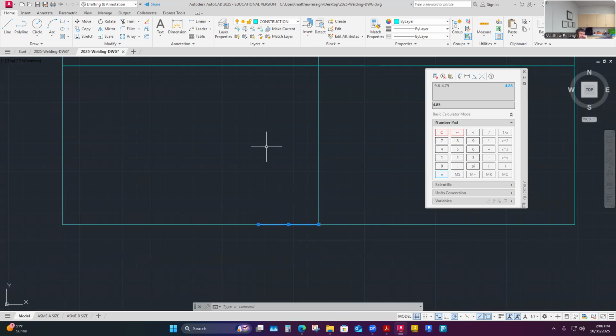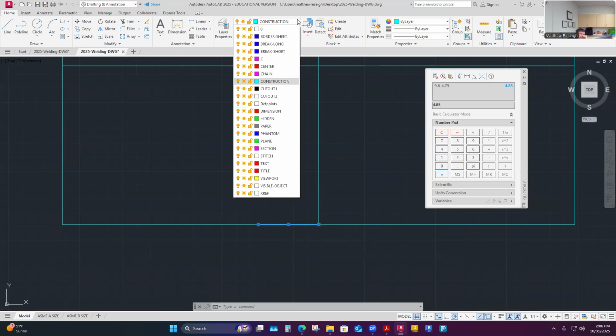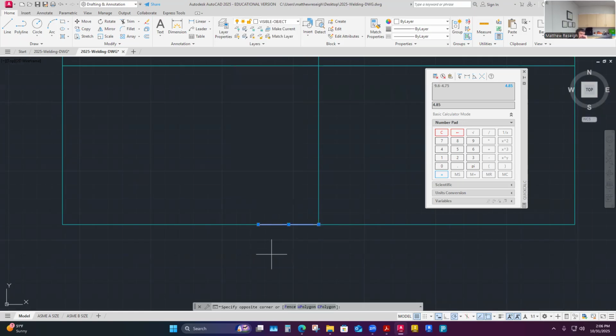And if you just have it selected while you come up here to your drop down list to draw on those, and you come back here and you select this, it will actually push it. And then I can escape now. It did turn it white. You can see that. Having it selected and then choosing a layer will push that stuff to the correct layer if you drew it wrong.